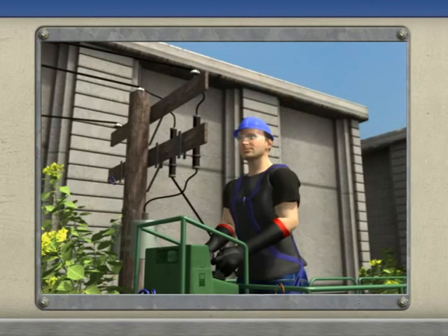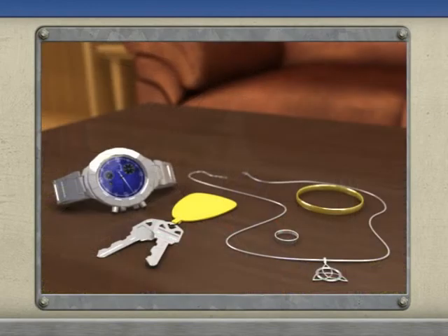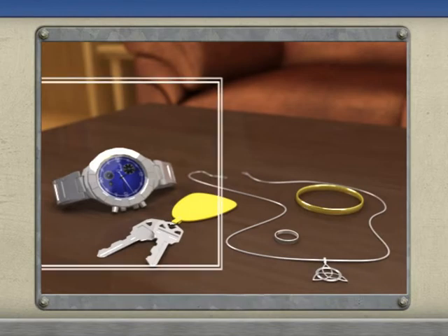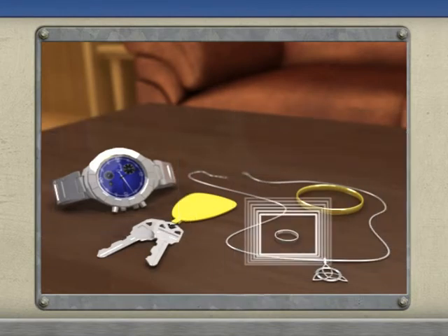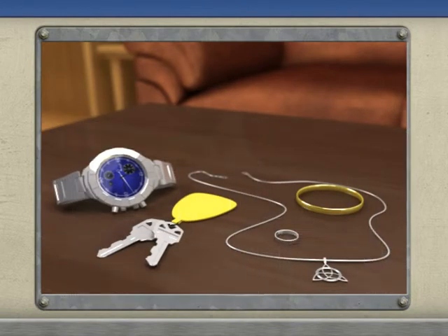Hard hats protect your head from accidental bumps, falling objects, and from contacting unseen overhead wires. They should be worn securely so they do not fall off. In addition to wearing proper PPE, always remember to remove conductive personal items such as watch bands, bracelets, rings, keychains, or necklaces.